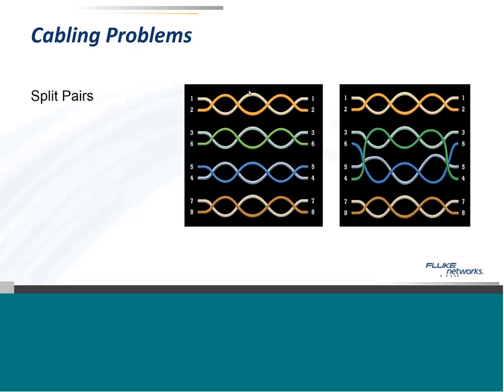If you put A on one end and B on the other, you've got a good chance of getting split pairs. So just make sure you always go with that. I think A is less common now. I think most people have gone with B. So if you're doing something new, I'd go with B. If you're doing something in an existing plant, figure out what you've got at the other end. And that's a very good question, though.